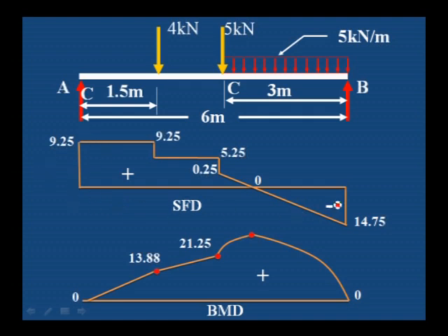This is the shear force diagram. What you can observe here, this is the RB value, shear force at B negative, shear force at A positive. This is a vertical drop at A, a vertical line at A as well as B, and then it is constant from C to D, and then you can observe here it is a drop.